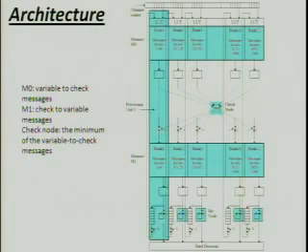This is the canonical architecture that I have been using in constructing the decoder. In this architecture, column partition is applied to divide the decoder into several parallel units, where each unit processes certain bits. This figure illustrates the architecture of the min-sum product decoder. Memory M0 stores the variable to check messages, and memory M1 stores the check to variable messages.